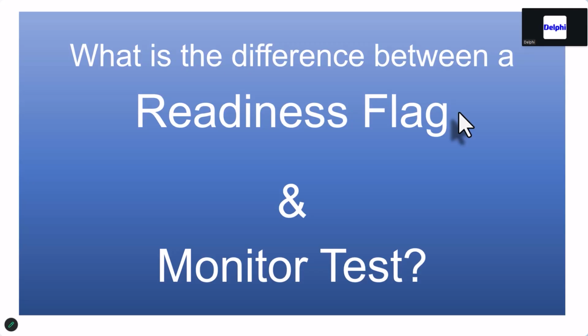So if someone calls me, and I get a lot of calls on this, saying I can't get this monitor to run, and particularly the O2 is an example, evap is another one, and they'll say, I can't get it to run, I'll go in and look at Mode 6, and I will see that a bunch of tests ran, but it hadn't finished.